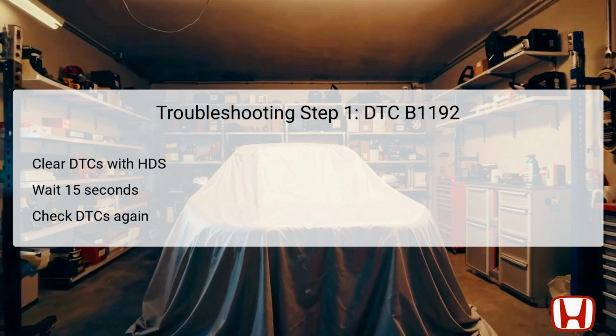If it does not appear, then the problem could be intermittent, suggesting the battery sensor may be functioning correctly at this moment. In this case, investigating for loose connections between the battery sensor and the GCM is the next recommended step.